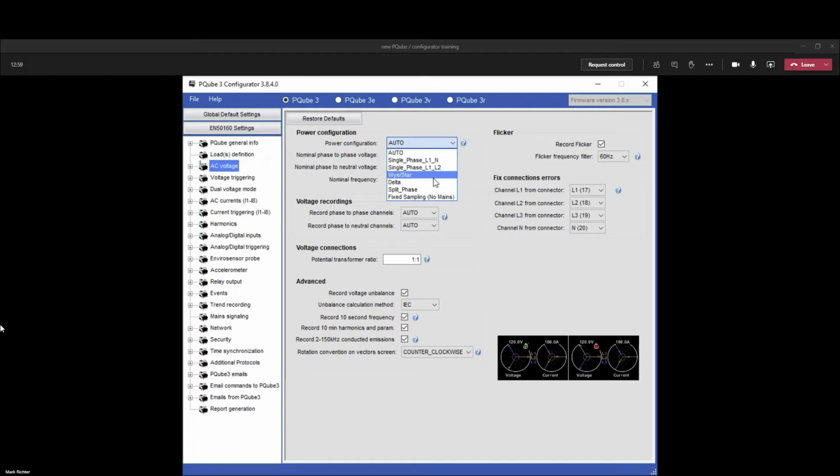So we're going to say your house is the simplest of connections. It's a delta. But let's just do Y, to make it more complicated. On a Y, your house is fed with a 480 circuit, right? And if you have a 480 circuit, your line to neutral voltage is 277, or 480 divided by the square root of 3.